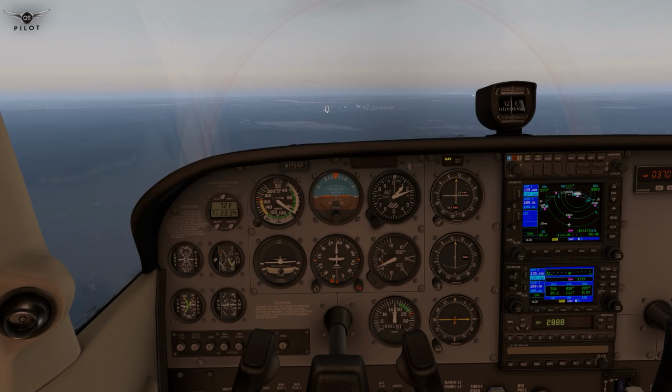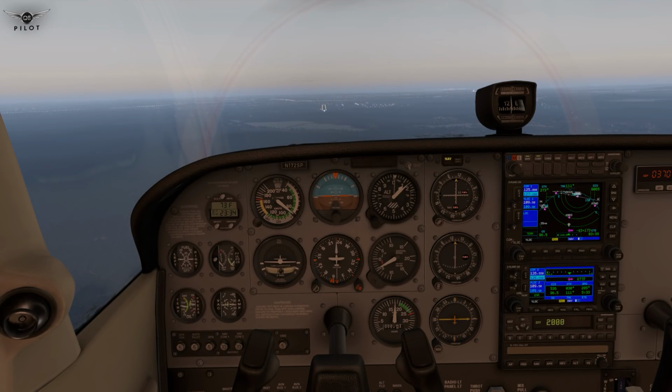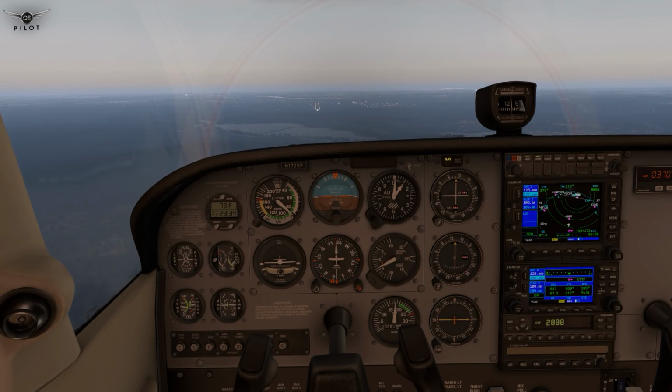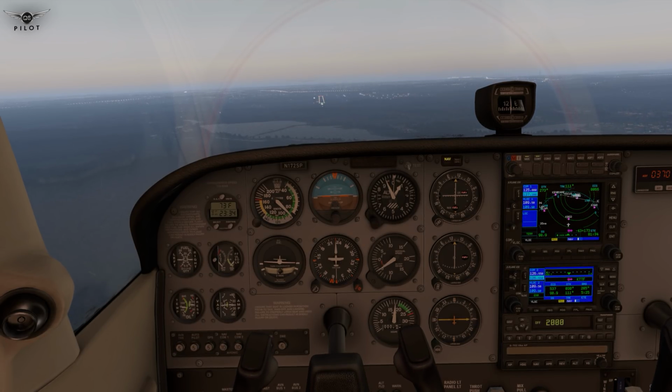We're at the outer marker. Alright, we're going to continue to descend now at about 500 feet per minute. And I am doing a visual approach, so the landing will be rated accordingly. It will be rated according to visual flight rules. And if you tune in the ILS frequency to nav 1, then it will rate you based on the instrument approach, which is always a nice thing.